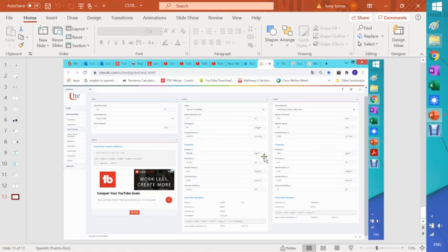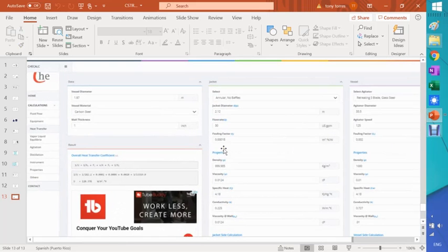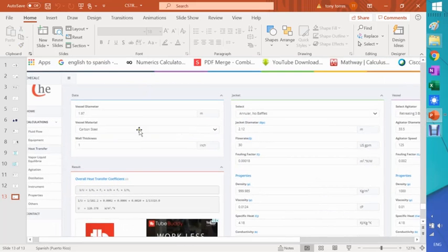Now, to do that, I like this web page. This web page is a chemical engineering calculation for how to get that U value, and it's kind of straightforward. It's divided in 3 sections. One of the sections is just data for the vessel, like the diameter of the vessel and what material you're using. The bad part here is that they don't use glass, but you will see in a second that there's a way to work that out.